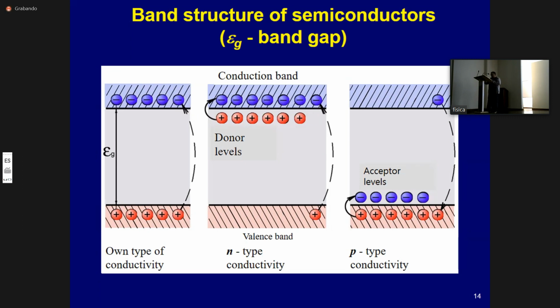After some time, an equilibrium state is established in which the resultant fluxes of electrons and holes are equal to zero. Under these conditions, a region is created in the semiconductor where the electrical resistance increases sharply and the electrical conductivity drops. This region with a low concentration of charge carriers is created.